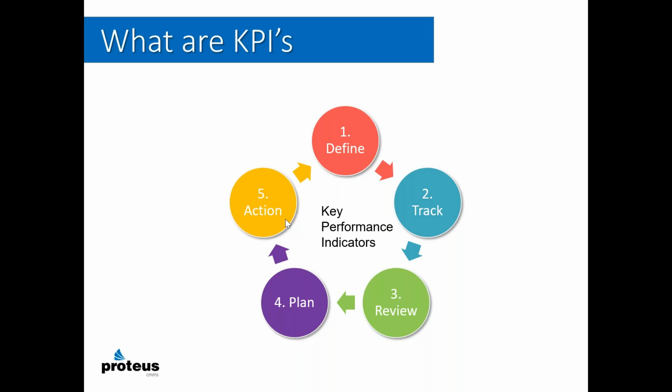They also wanted to measure how many times I have a hot cold call to a given room. In a hospital environment, I had a client that measured hot cold calls. The first time, the technician assumed it might be a thermostat problem, so they replaced the control on the wall for $75 or $80 and assumed the problem was fixed. The next time they get a hot cold call to that room, it's critical that the next technician realizes that somebody already replaced the thermostat.